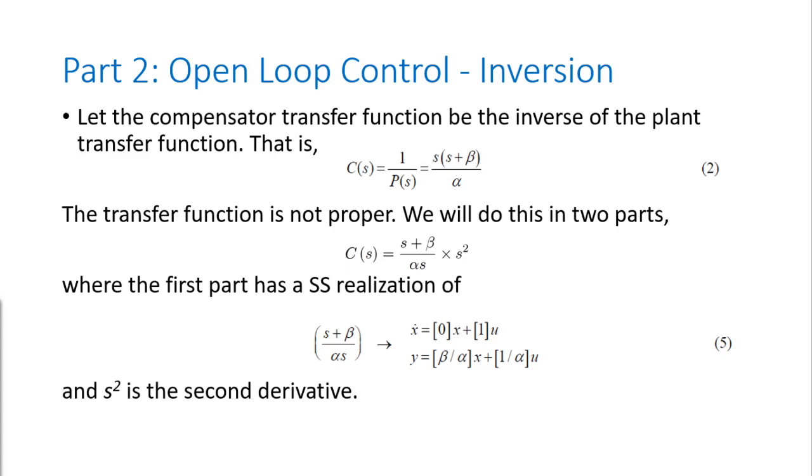We talked about inversion. What is it? Namely, you have a compensator which is exactly the same as 1 over the plant. So what does that do without the feedback loop? You have no sensor, you're basically just doing it blind. So what you're doing in essence is you calculate the voltage that you need based on the desired position, and you put the voltage in.